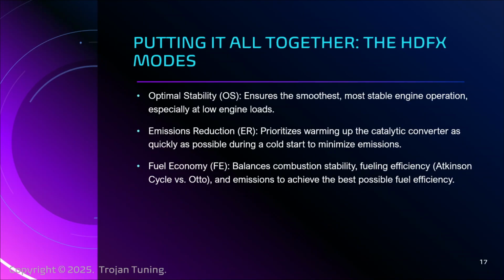When you start looking at the four-stroke cycle or the Otto cycle, you learn that there are two modes, right? One is power, lots of it, and how you do your timing and how you adjust your cam intake and exhaust angles, right? We do one set of things. If we're just going for economy, though, we use the camshafts in a very different way, referred to as the Atkinson cycle, and that has things happening almost offbeat.